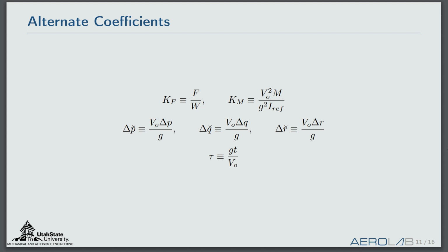And we're not the first ones to notice this. This was actually something that was noticed by Phillips in his book Mechanics of Flight. He goes into a little bit of detail as to why the pitching rate should be non-dimensionalized this way, and he calls it a dynamic pitching rate, and that's the methodology that we follow. We call these dynamic rates. And he talks about how that can be related to the Nz acceleration component on an aircraft. And once again, for more information, I direct you to the paper as well as to the work by Phillips.